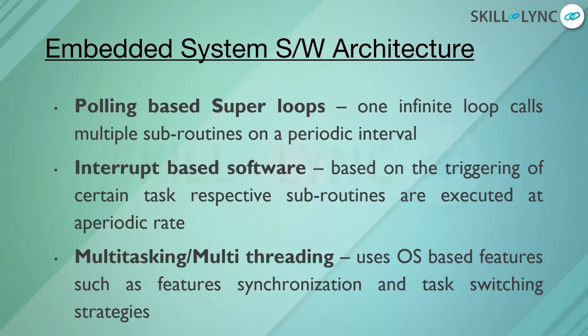These interrupt-based software are ideally required for triggering the respective subroutines, which are executed at a periodic rate. When I say a periodic rate, let's say I want to measure a rotating disk. It could be coming from a motor, or from an engine, or from any sort of mechatronic system, where whenever there is a signal coming from the rotation completion, I need to go and count, or go and measure.